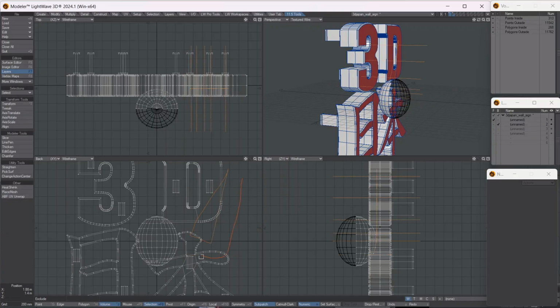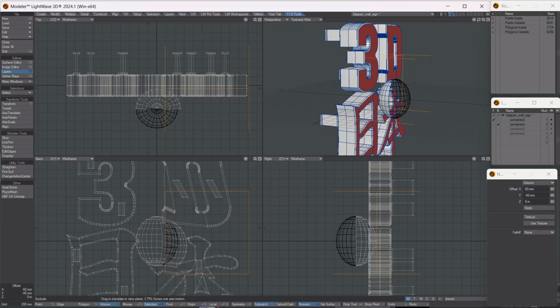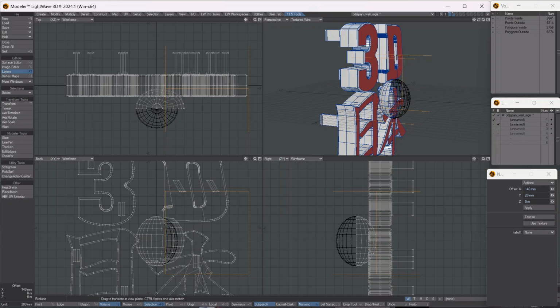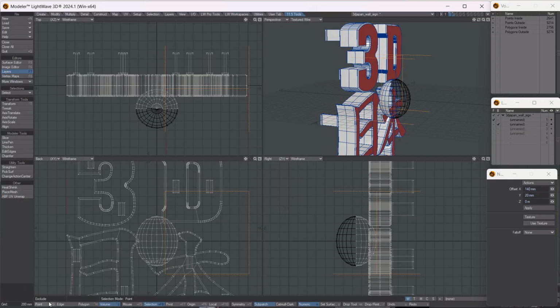You can use the right mouse button to drag and select an area, or the left mouse button to select a square or a rectangle, I should say. And then anything that you do will affect inside that area. So if I hit T for move, then it'll just move points that are inside that area. Let's undo. And then you also cannot get out of this with spacebar. You have to manually click one of the other types down here.